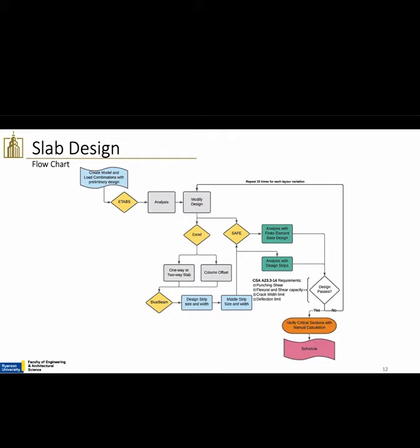The following flow chart was used in the design process. The preliminary dimensions and load combinations were inputted into our ETABS model. We run the analysis to identify any modifications required, and we add them onto the design. We bring this data into Excel, or we could also export it into SAFE and use the finite element-based design for complex layouts.